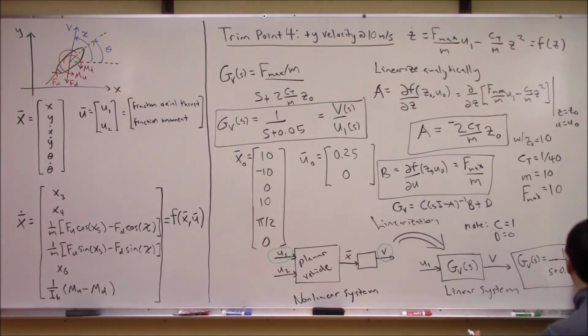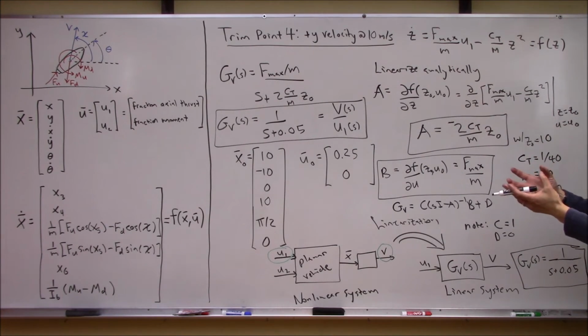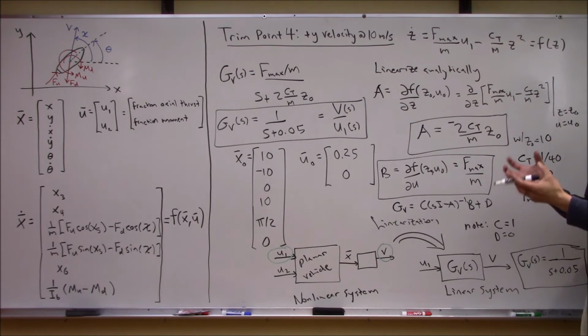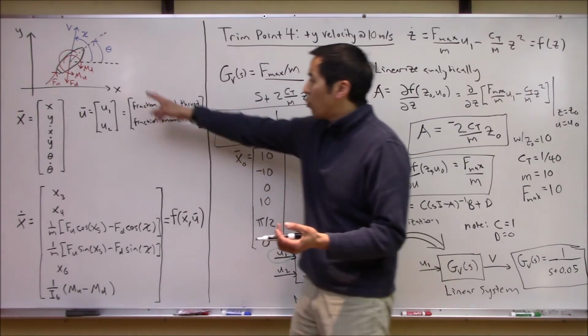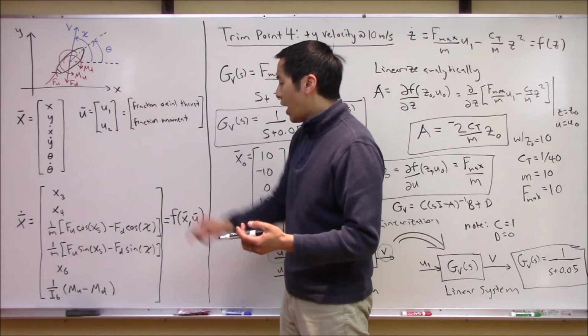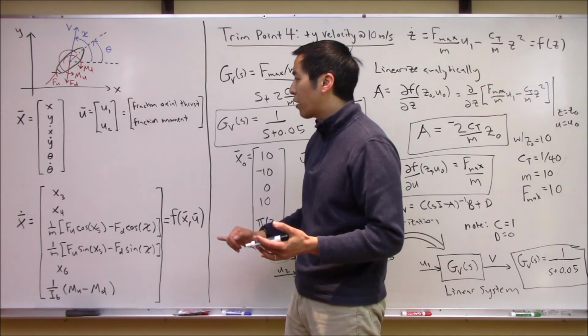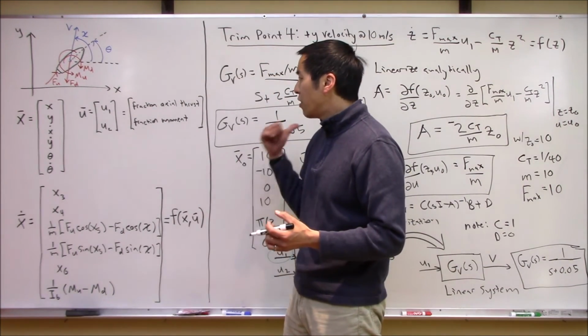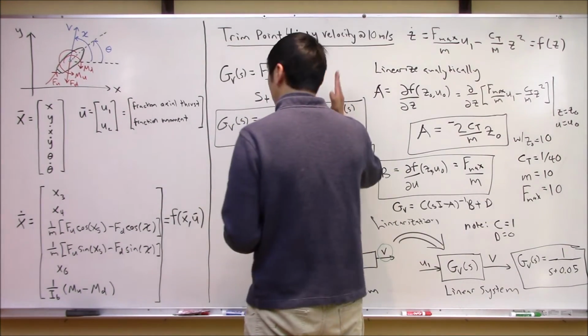Oh, well, I guess I should change this down here, right? This is what the linear analysis tool gave us, right? So everything is the same. And again, it's actually fascinating that this system's dynamics change depending on the operating point, which makes good sense if you think about the way this system is set up, right? We had this nonlinear term of drag. That's actually what's coming into play in this one-dimensional case where the vehicle is just going straight, right?